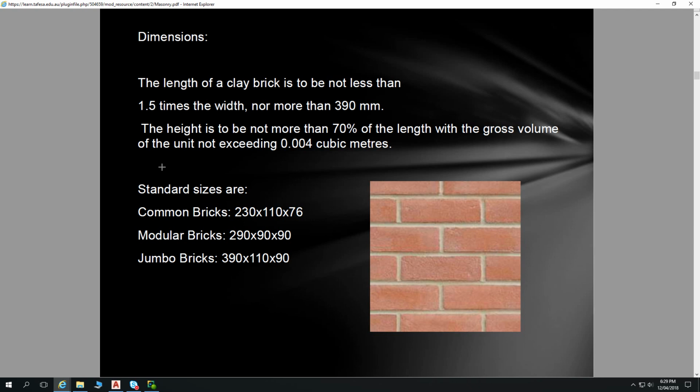You'll probably notice, and you'll continue to have this reaffirmed as you get more and more involved in building, how often the increments of 300mm turn up in buildings. Things like our plasterboard sizes. Can anybody tell me some standard plasterboard sizes? 2400, 1200. Yeah, 2400, 1200. Divisible by 300mm. So 4 lots of 300mm or 6 lots of 300mm.